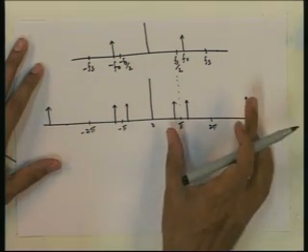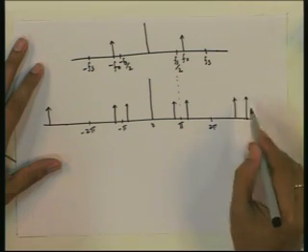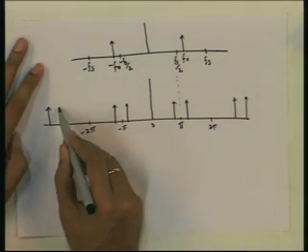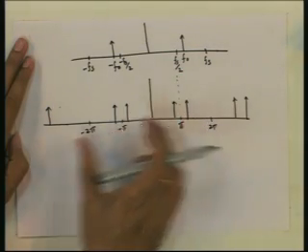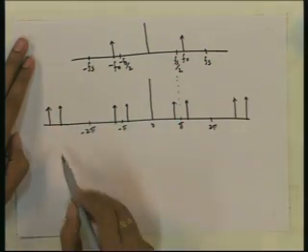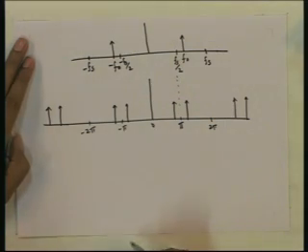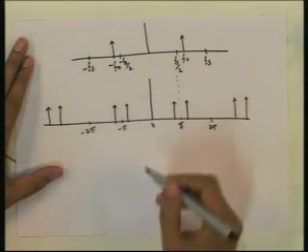And similarly, when this is shifted to 4 pi, we will get something here and another component later, and when this is shifted to minus 4 pi, we get one component here and another component beyond. So, this is the DTFT of the sampled signal.